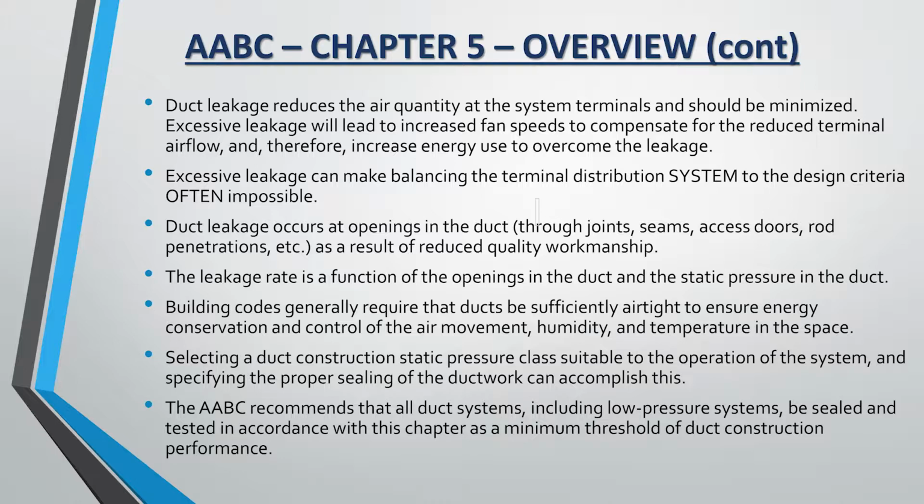Duct leakage reduces the air quantity in the system to the terminals, and should be minimized. Excessive leakage will increase the fan speeds to compensate for the reduced terminal airflow, therefore increasing energy use to overcome the leakage. Many times you get involved in a system and it's 20,000 CFM, the unit's only putting out 18 or 17 to the diffusers, terminals.